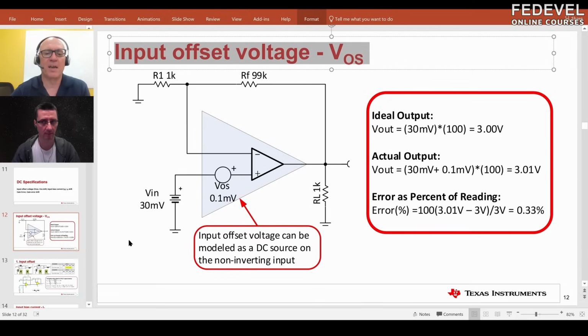So that's a common thing to do, but you can't easily calibrate out things like temperature drift or power supply impact on offset. Some of these secondary things that cause offset to shift are more difficult to calibrate out. So you could maybe calibrate for some kind of average offset, but the temperature influence would still be there. Yeah, exactly.